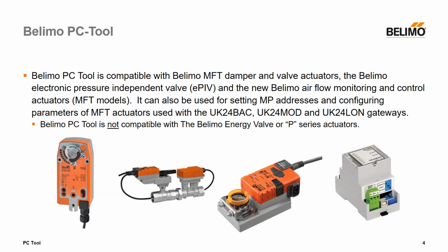It's designed to work with near field communications. And on the P series actuators, you'll actually see a little NFC logo where either you can lay an Android phone on it and it'll communicate directly with the NFC chip, or we have a little gateway that if you're using an Apple phone, you can attach that to the P series actuator where the NFC logo is, and using the Belimo Assistant, you can configure those P series of actuators.